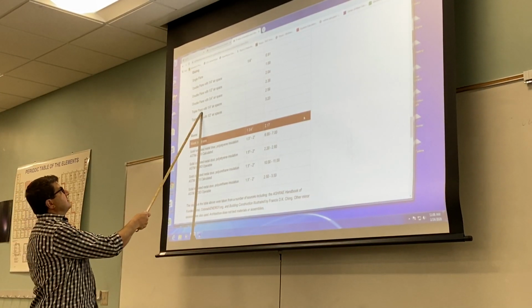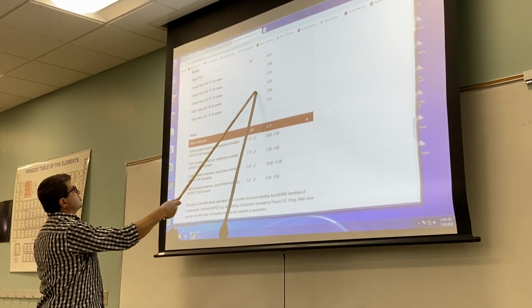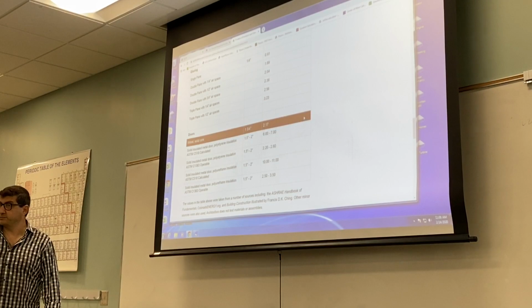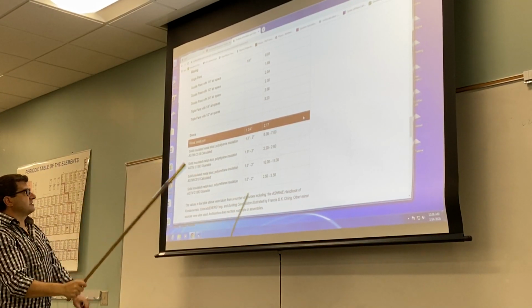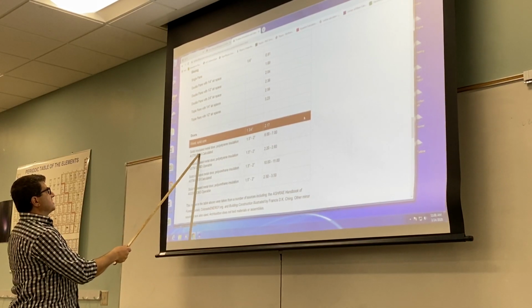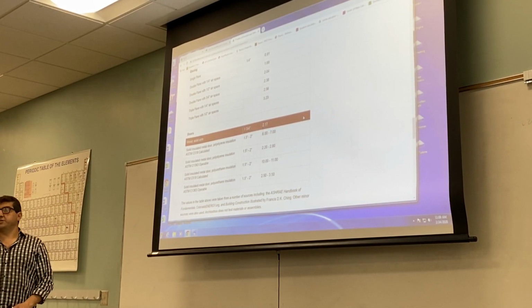Triple pane with 1/4 inch, 2.56. Triple pane with a 1/2 inch, 3. Wow, I didn't even know there's a triple pane. So three layers. Doors: wood solid core, solid insulated metal door. So you see even that, you're losing heat through the door.